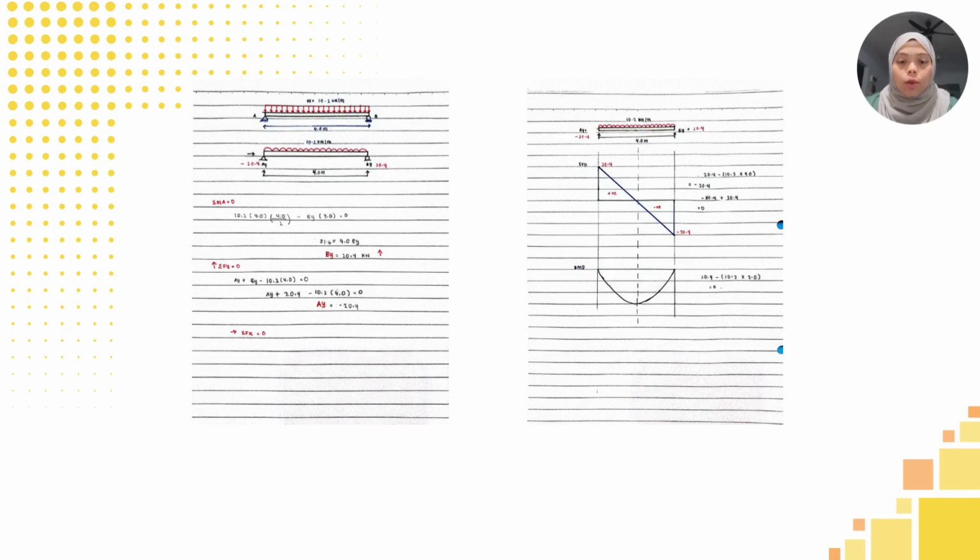The shear force diagram shows the maximum shear force at a support and zero shear at midspan. The bending moment diagram has a parabolic shape with the maximum bending moment occurring at the midspan. The shear force and bending moment come from the same loading. They represent different quantities and have different units.